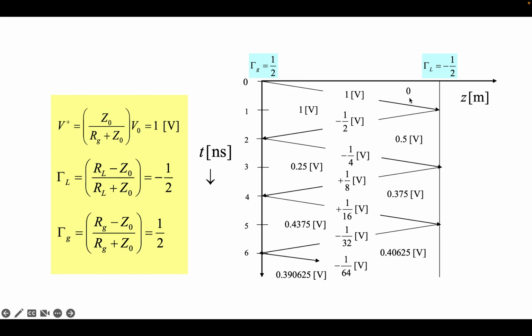Okay, great. Now, as I told you, you can consider them as zones. So here the voltage will be 0, and now you go here, so voltage will be 1 volt in the whole zone. Then if you go down here, the voltage will be 1 minus half, 0.5 volt all over here. Then if you go here, it will be 0.5 minus 0.25, because it's minus 1 by 4, so this whole region is 0.25 volt. Then you go down, so 0.25 plus 1 by 8 will be 0.375 volt. And then you go more down, this zone will have 0.375 plus 1 by 16. Okay, so this is how you will solve such problems.